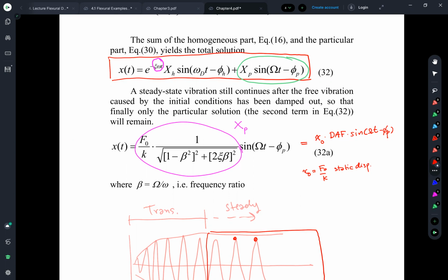After you multiply your static displacement or static bending moment with the impact factor, that is already your dynamic displacement or deflection or dynamic bending moment. It takes care of the effect of the truck traveling on the bridge with some speed already, not a static truck anymore. You see, the idea of the DAF is applied in many applications as the design code I mentioned.